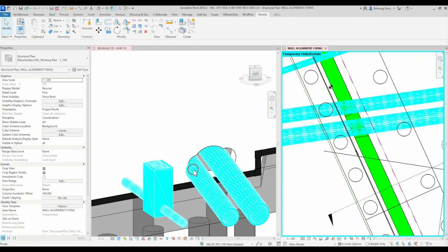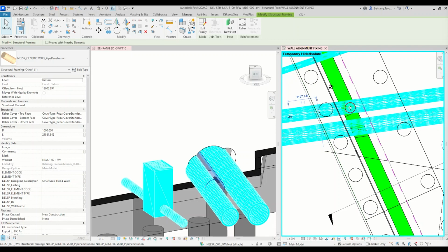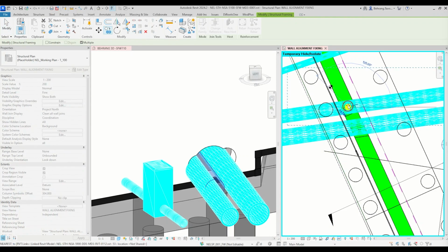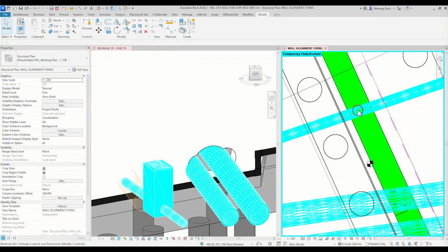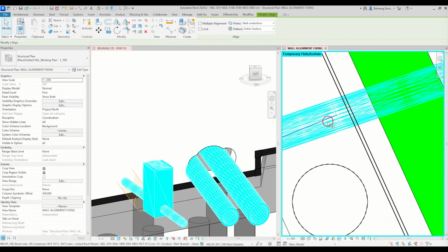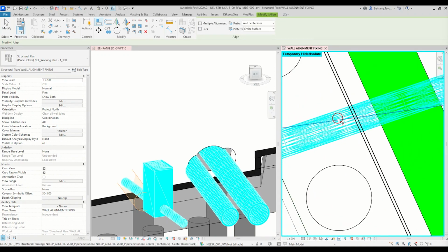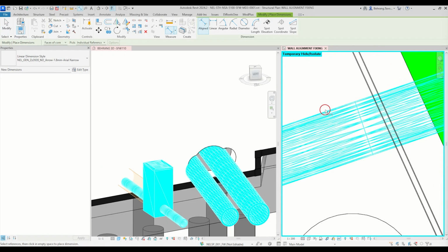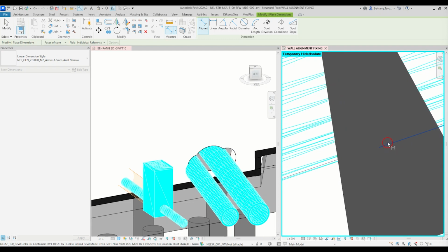So we have another one there. Let's also select one of these here, and selecting this tab, CO for copy, pasting there. Let's align it, AL, should be with this line, and that one. What's the size? DI for dimension. Let's see that. How much is the size of that? We need to pick this line.